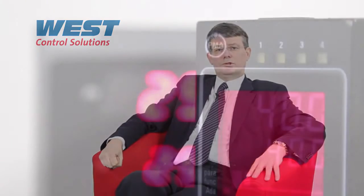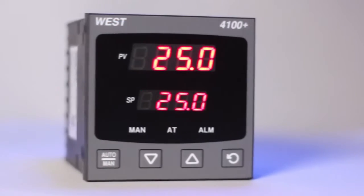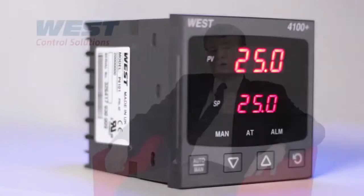It might seem that a long cycle time is always good, as it reduces the amount of wear on the mechanical devices in your process. However, a long cycle time is not good for control. If you set the cycle time too long, the process will begin to oscillate, a bit like it did with on-off control. In fact, if you see the process oscillating with the same time period as the cycle time, it's a good indication that you set the cycle time too long.